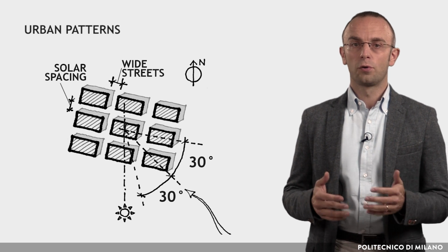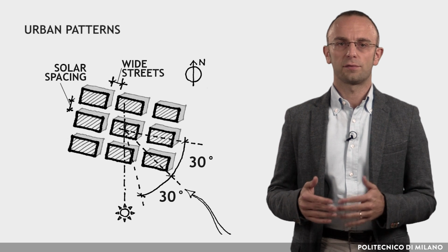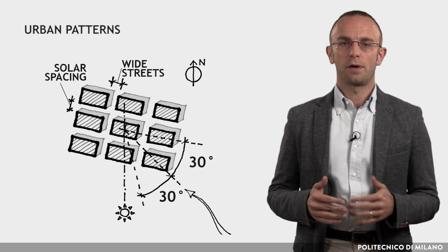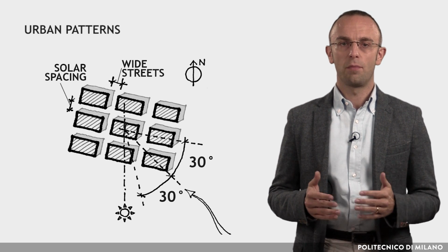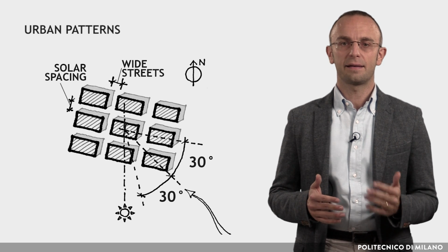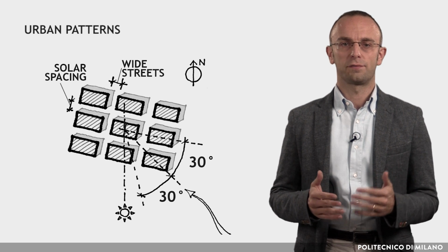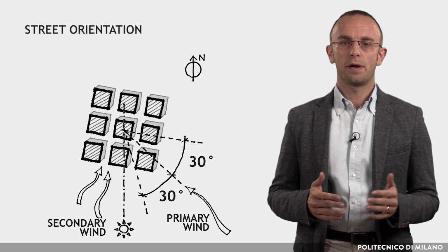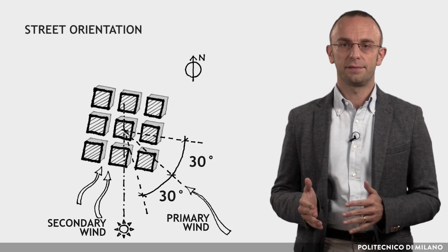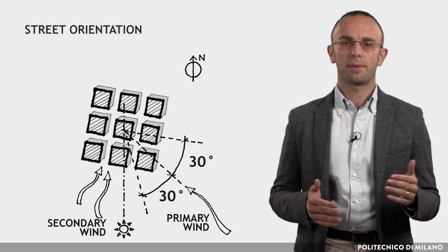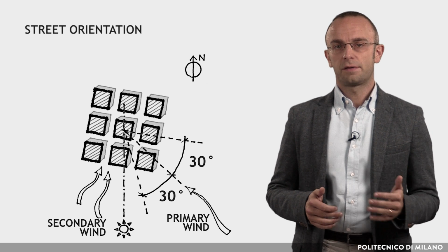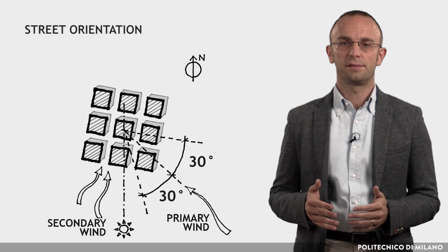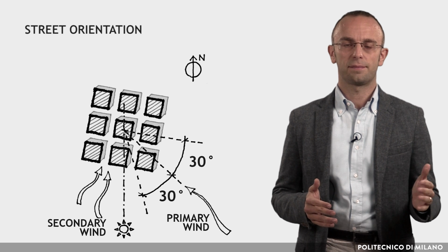More in detail, in hot, humid climates, loose urban patterns should be preferred in order to maximize cooling breezes. Breezy streets oriented to the prevailing wind maximize wind movement in urban environments and increase the access of buildings to cross-ventilation. To maximize air movement, primary streets have to be oriented at an angle of 20–30 degrees in either direction from the line of the prevailing summer breeze. Further, it should be taken into account that dispersed buildings with wide open spaces preserve each building's access to breezes.